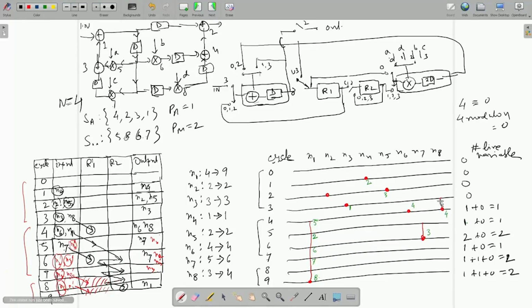So, N8 will be coming from the multiplier output, from this output line, then stored again by one cycle, so that it will touch this here at what cycle? Cycle 3. Cycle 3, N8 is born. If it touches this, it will take the multiplier output, which is this N8, cycle 3. It will be stored in R1 and then consumed.